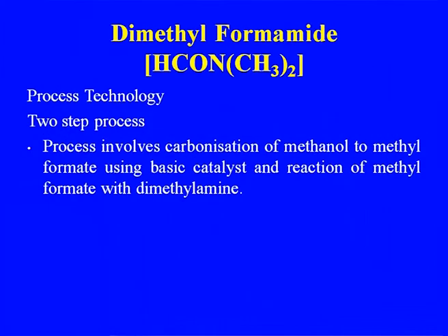This is the two-step process. The process involves carbonylation of the methanol to methyl formate using a basic catalyst, and reaction of methyl formate with dimethylamine. So, this is the two-step process which we are using for making dimethyl formamide.